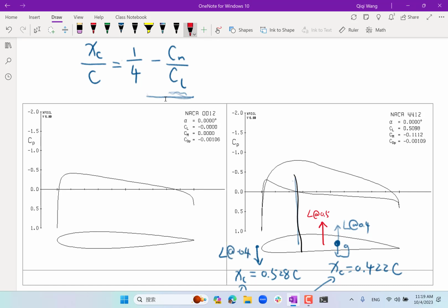And at minus 0.5, my center of lift is symmetric to this lift. So that's my lift at minus 0.5. Any questions on why the center of lift is like that? Okay, so I'm just reversing the sign of this term. As a result, the center of lift is basically symmetric to the quarter chord, right?